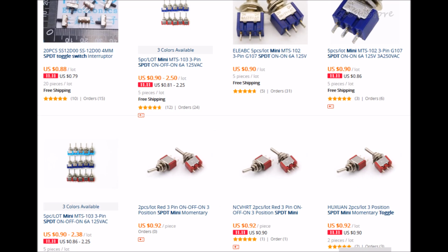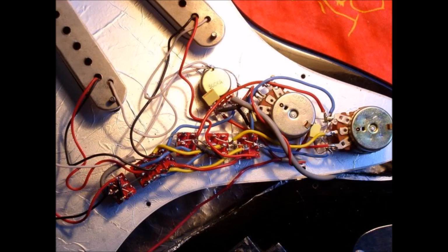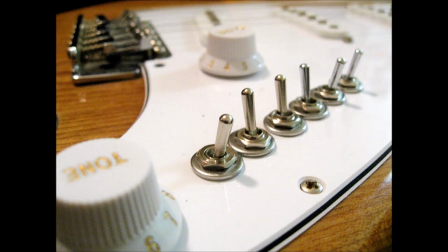The biggest advantage of this system is its low cost, availability of parts, and the ease of construction. Despite the number of switches, assembly is very easy, and employing a point-to-point floating wire construction, also known as spaghetti wiring, will suffice. The switches are available in different profiles, and the entire switch system with phase switches can fit in the switch cavity of the guitar, if sub-miniature toggle switches are used. Since the switches used are usually sealed toggle switches, this system is quite robust.